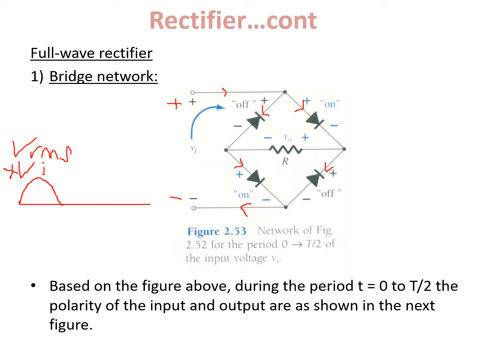Okay, and go back to negative, and from here it will... this diode will be on. This is positive and negative. This one will be off, this one on and off. So now your circuit is left with just this one. Which diode is off is an open circuit now. Which one is on is a short circuit.